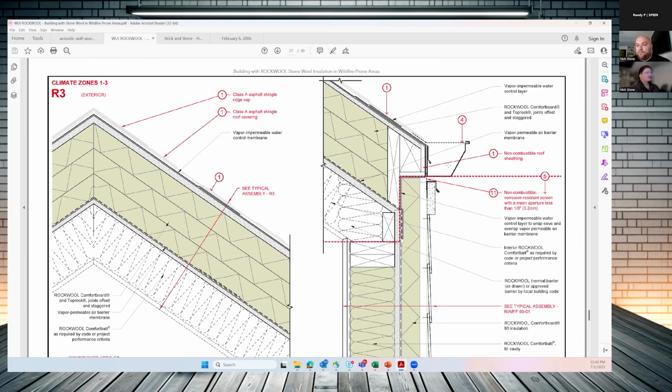Yeah, we've talked to the end of the earth on the webinars here about grading of insulation and what third parties have to look for. So my question would be, since there is a little bit of difference in how it's installed to be correct, I'm sure you have training programs so that your installers and suppliers are trained the right way to do it. Because I don't know if it's true anymore, but these guys used to get paid by the piece, and the faster they went, the more money they made in a day. They just compressed the heck out of it, and it destroyed the whole integrity of the insulation. Rock wool and stone wool products hold their shapes better, so I'm sure they're trained on how to do it correctly.